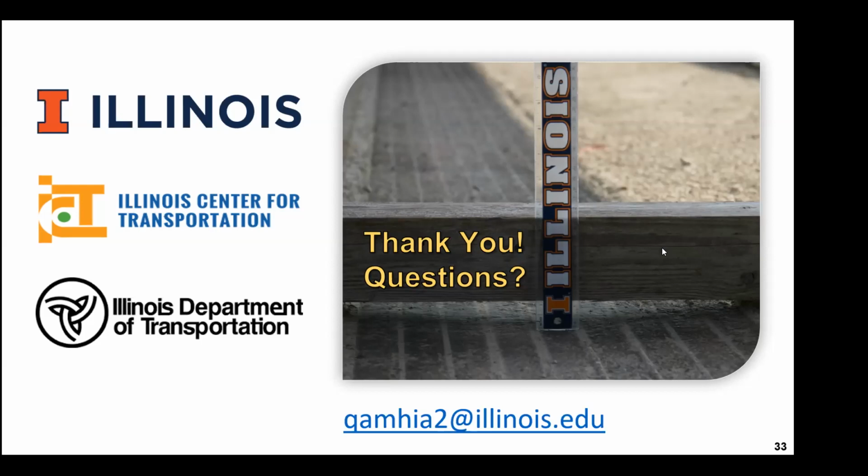The other thing is your question about the accelerated pavement testing and how it contributes. Basically, it just gives you a step ahead, or more information than just lab samples. With lab scale, you're more limited to the size of your experiment. As Isaac also had in his question, you're more limited to the effect that you see, like the short-term effect. When you go to accelerated pavement testing, that's a step further, because now you're building full-scale test sections. So you're eliminating the size effect.